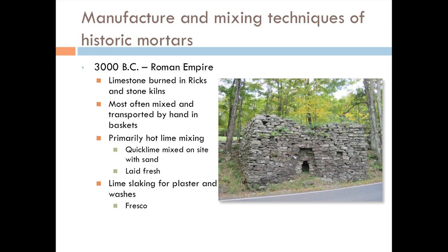So the very ornate plasterworks you might see in Europe, and to some degree in highly ornate buildings in the United States, that's what they were using. Sometimes it would be aged with gypsum, but in very small amounts. The reason gypsum is not used exteriorly is because it doesn't hold up. That's why if you put drywall outside, it's not going to work. It's not going to hold up to anything. It reacts with water.